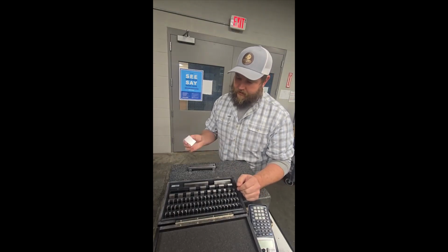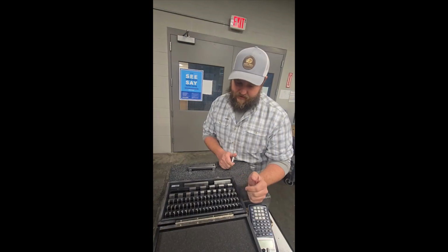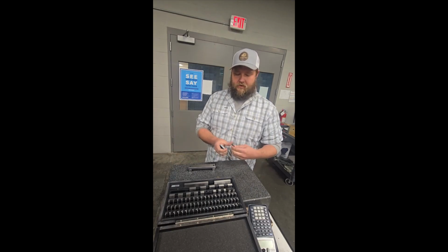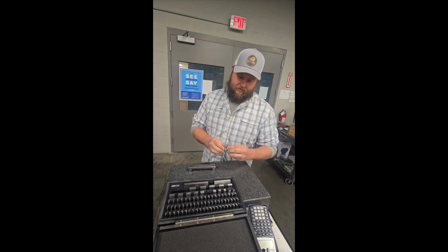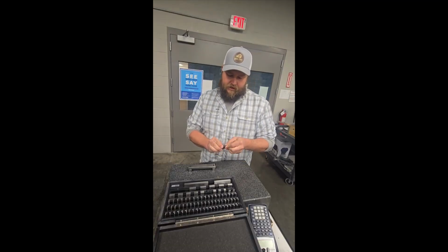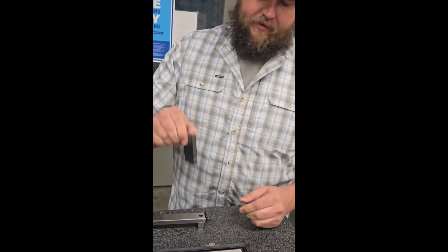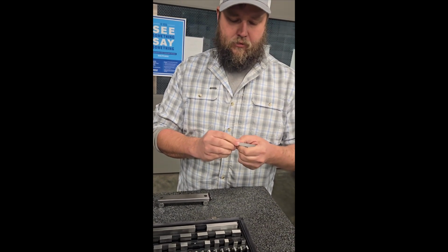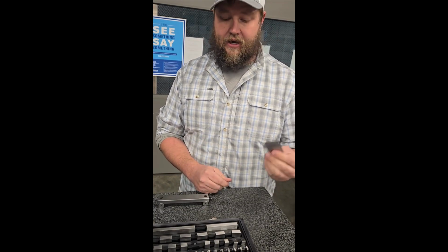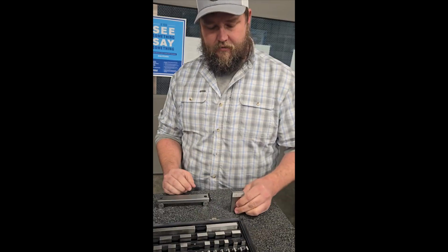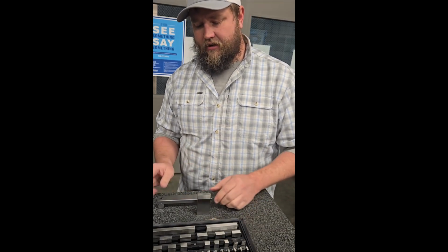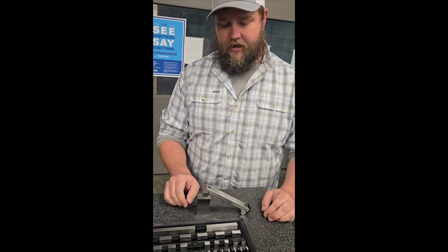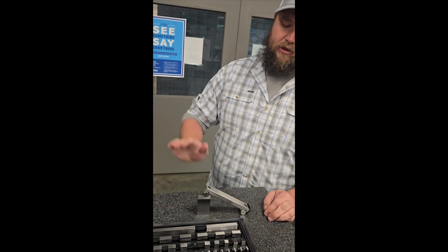In order to ring them, we're going to grab a 2-inch gauge block and a 1/2-inch gauge block, and I clean them, make sure they're not dirty, and then I go off to the side and rotate. If you have to, you come back. They'll bond. They're not magnetic. It's more of a molecular bond in a vacuum. But now the blocks are rung. We can stack it and stack our sine bar on there, and we get a 30-degree angle based off of the plate and sine bar.